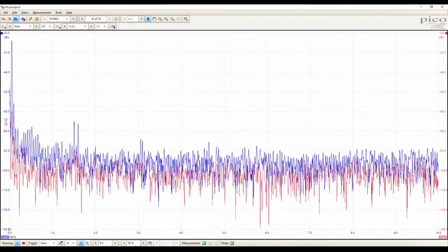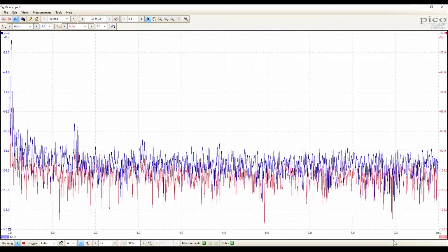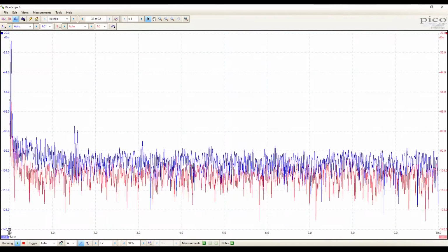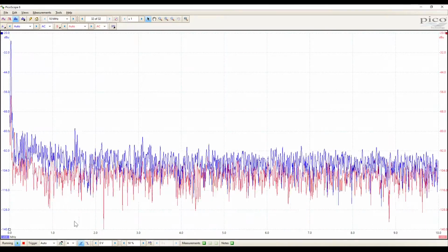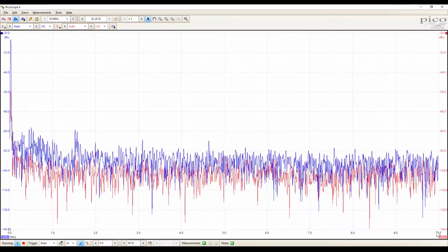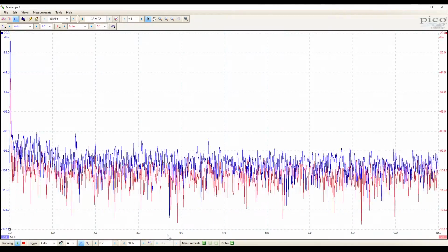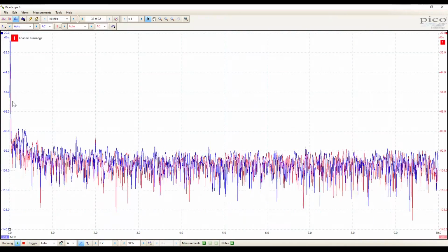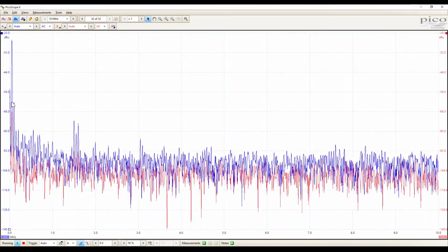It's in decibels down the left hand side, and then we have our frequency along the bottom. By default that frequency goes from 0 to 10 megahertz, and the scale's in megahertz in the bottom left there. Remember, I think we set it to go from 1k to 10k, so we're measuring in this tiny little range on the left.